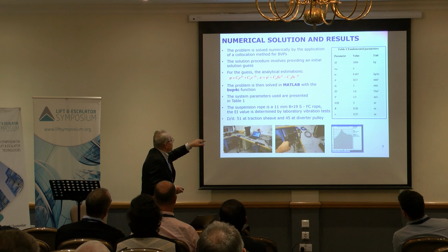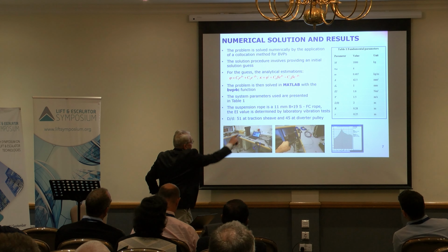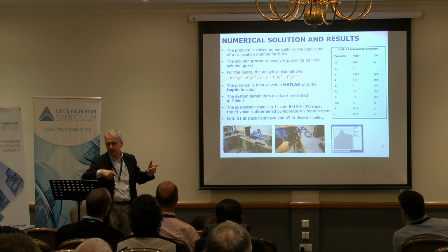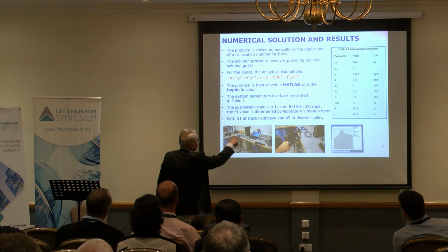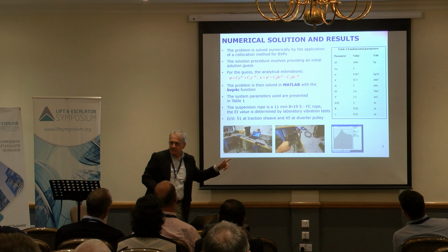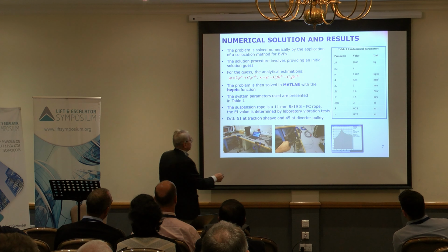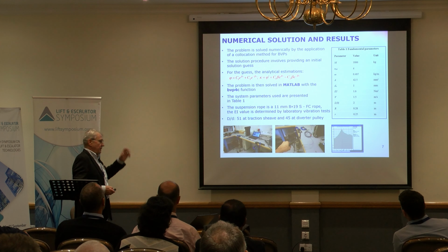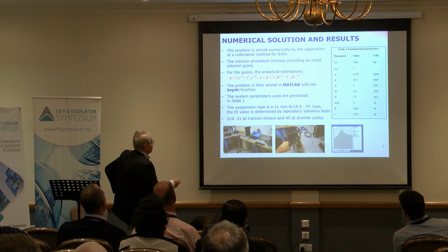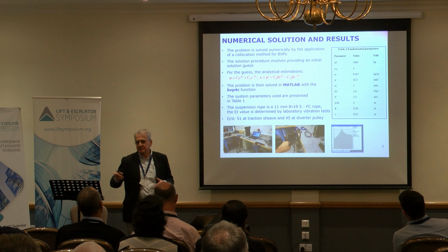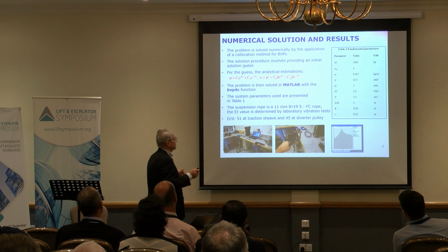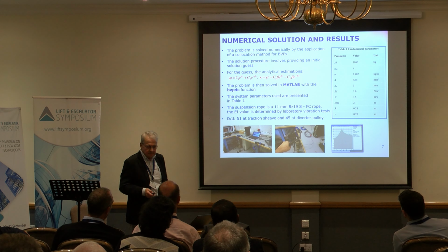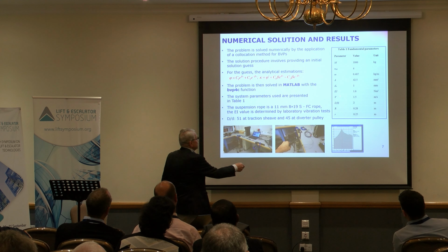And this will be solved for a set of parameters here on the right hand side. For the lift, you've got the mass of the car, because we are looking at the car side. Mass, number of ropes, mass of the ropes. In this example, this rope is used: 11 millimeter, 8x19S FC rope Draco. So 11 millimeter is the diameter of the rope. Then we've got some other parameters here, for example, speed. This solution will be dependent on speed, so we need to bear in mind that there are centrifugal forces involved. One aspect which I want to mention here, and a difficulty, is this parameter EI.